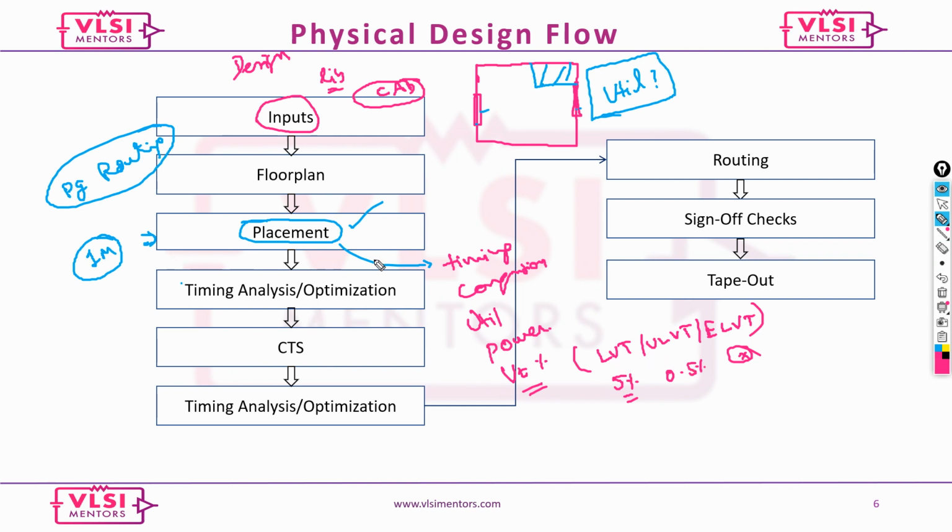So placement is basically targeting the timing, congestion, utilization, and then power, and then VT percentage, and there are many more aspects. Okay. And once you're done with your timing and placement, the next step is something that we call clock tree synthesis.